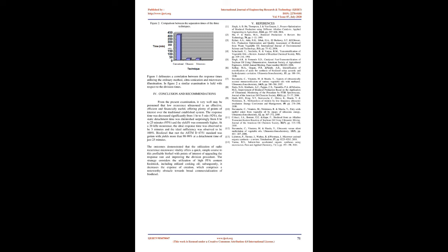A comparison between the reaction time, static separation time and yield % on using ultrasonic mixing versus mechanical mixing is shown in Table 1. The reaction time was decreased significantly from 1 hour to 5 minutes, 92%, the static separation time was decreased remarkably from 8 hours to 25 minutes, 95%, and the yield % was generally higher.